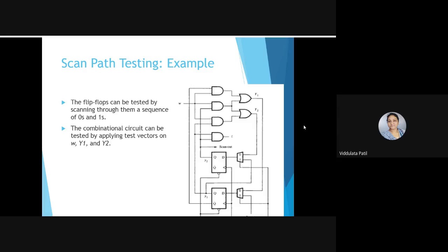And then for the next clock cycle, they are scanned out. So again we are using a scanning mode here, taking the output of this flip-flop and checking the scan-out output. Depending on this, we are checking for one test vector.